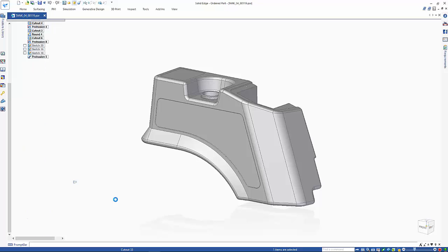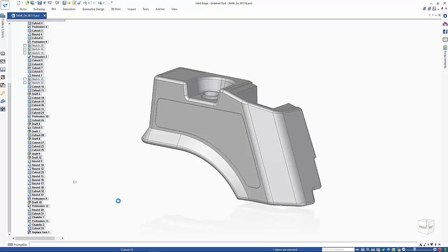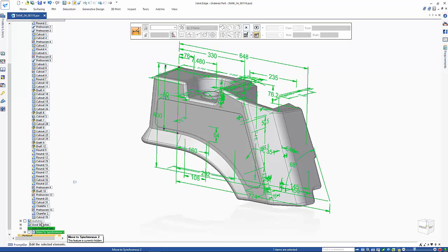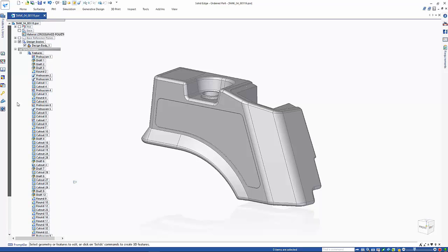As well as the geometry, sketch dimensions get migrated to synchronous. You'll find that some of these dimensions are actually irrelevant to the 3D geometry. These dimensions collect here so that they can be deleted in one easy step. Now let's make the required design changes on this fully synchronous model and see how it goes.